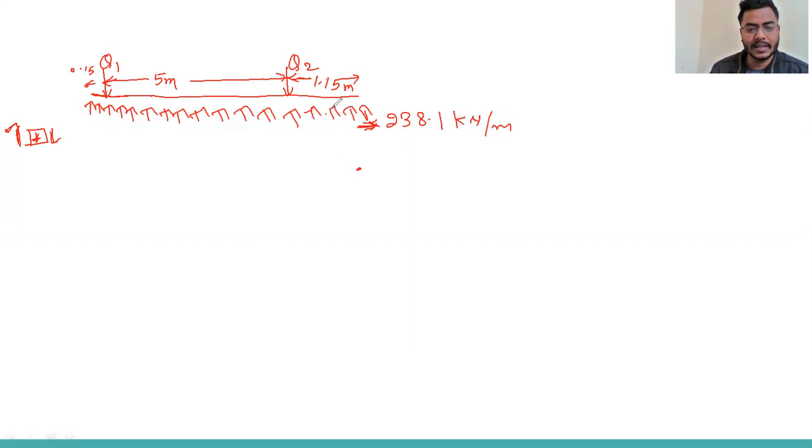You will see here there is an upward direction load. So this will be negative. We can give some names: this is the point A, this is the point B, this is C, and the end point is D. A, B, C, D. So the shear force at point A, there is no point load acting, so that will be 0, right?